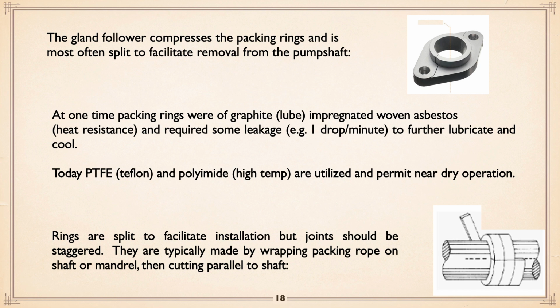Looking at the parts, there's the gland follower, which is used, you can see the lines on it, is usually split so you don't have to take it off the end of the shaft, take the pump apart. You can just pull it apart and there it is.